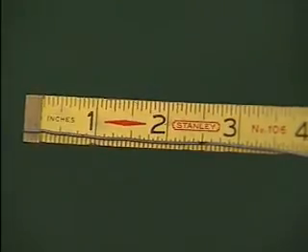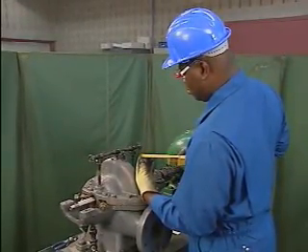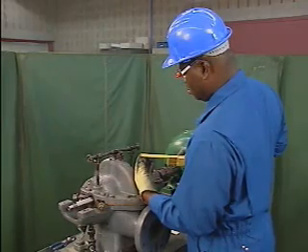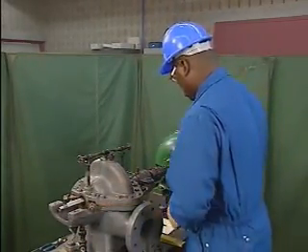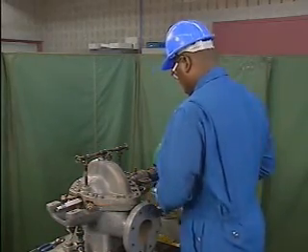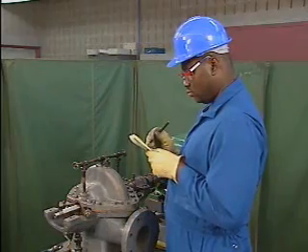He removes the wire and measures the distance from the mark to the end of the wire in order to get the depth measurement. Since this stuffing box contains a lantern ring, to get a true depth measurement, the thickness of the lantern ring must also be measured. This thickness is then subtracted from the depth measurement of the stuffing box, and the result is the actual depth that must be filled with packing rings.